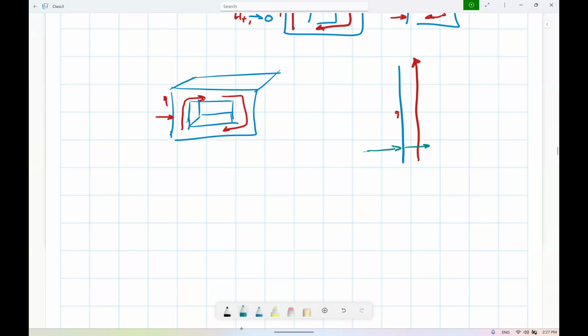So I can tell you this. If I see a boundary which is magnetic material, non-magnetic material, and the field is not perpendicular, I would say this is wrong. If I see a boundary, electric conductor, non-conductor, and the field is not perpendicular, I say something is wrong. If I see field inside of a conductor, I say this is wrong. But it has to look like perpendicular. It should not be 100% perpendicular.